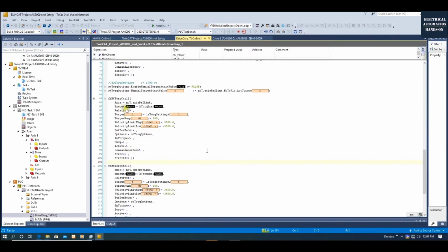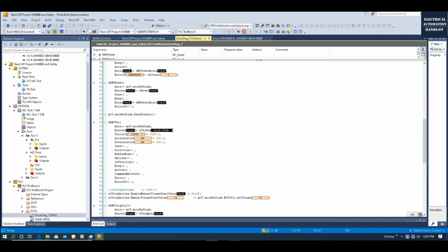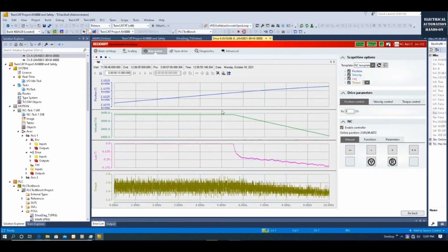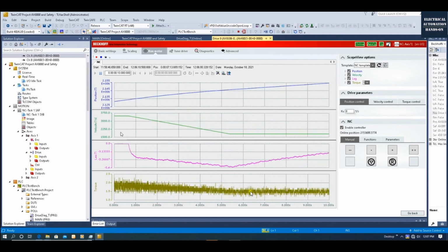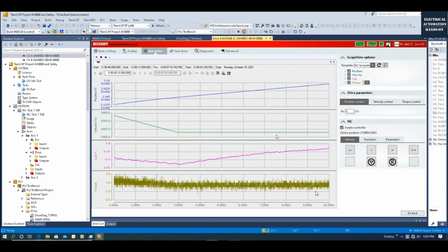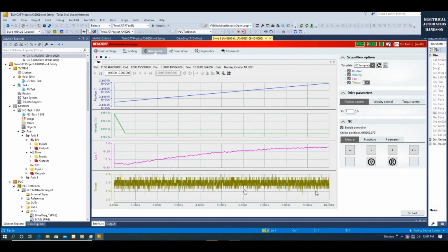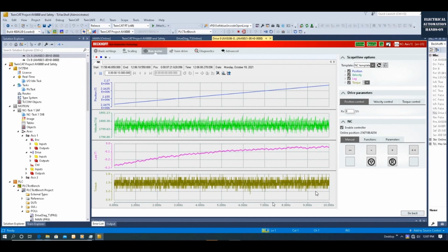So as we can see, if we are using two torque control instant function blocks, using a different set point for each function block, they can switch back and forth. So the new set point can be updated and delivered to the system. This is the torque control function block. And now if we switch to the velocity again, the system can smoothly switch to the velocity. We can see the speed go back to 1800 and the torque will go back to the actual torque, 1.6, like a regular run. So switching this mode can go back and forth smoothly.